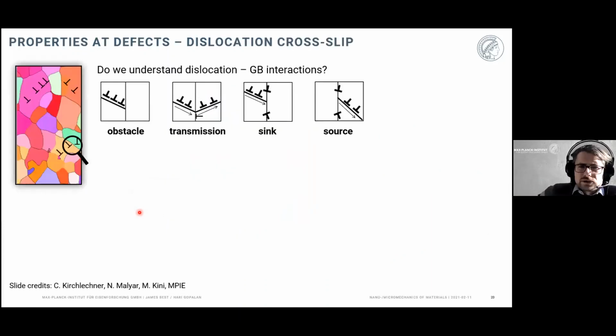And so one way that we can look at this is that we can think about having a material. So we're taking a piece of polycrystalline material now. Let's say it's copper. We know now that polycrystalline copper will have a number of these different grains in the structure. So they all have their different orientations. The copper will also, as we know, have a number of dislocations within the structure.